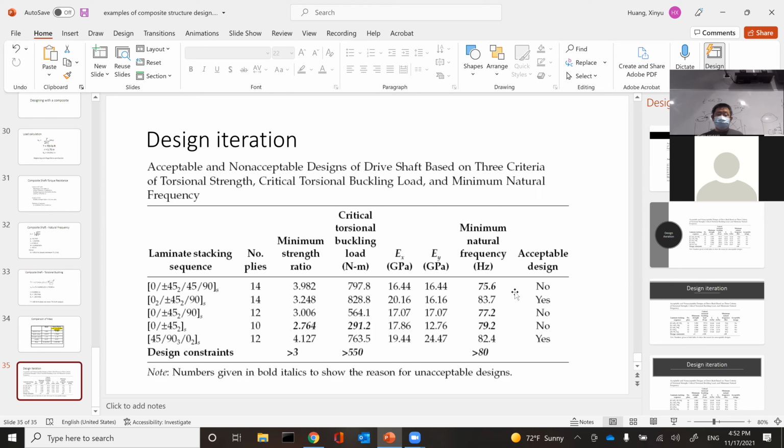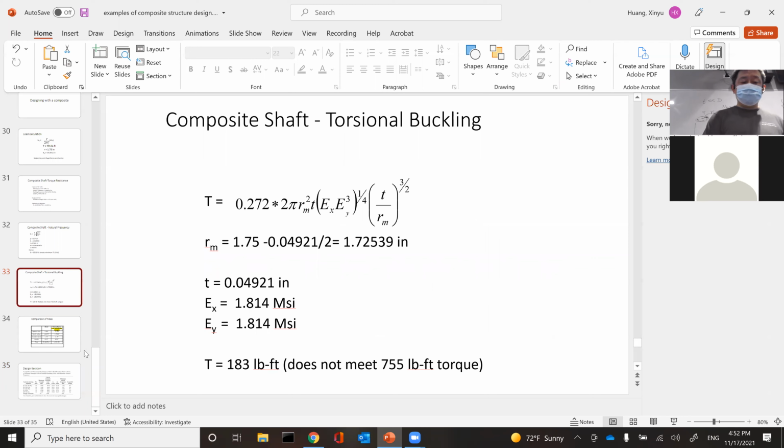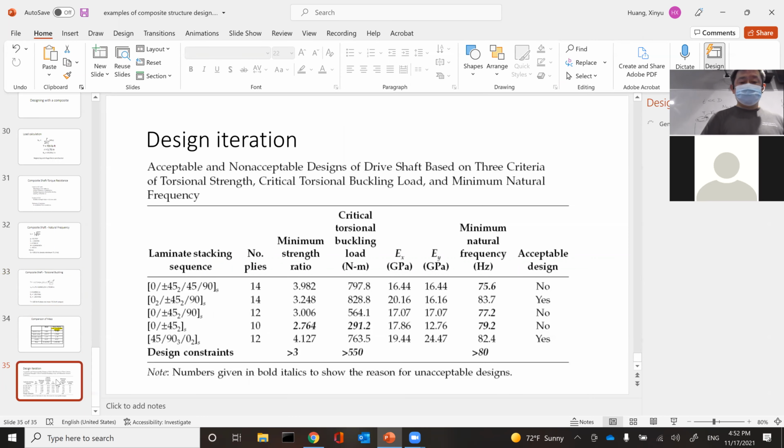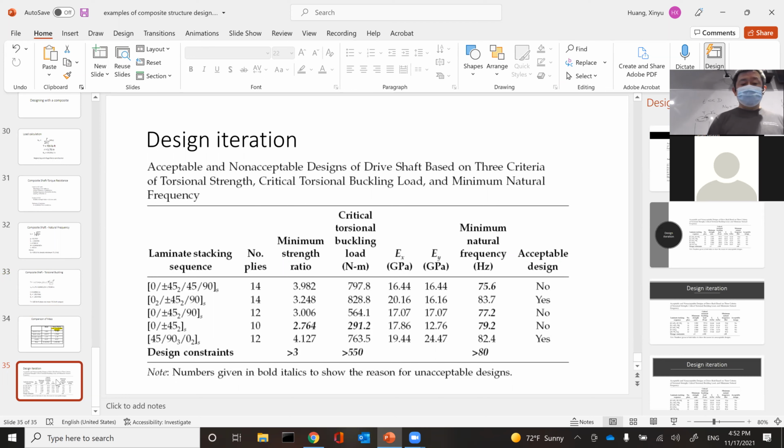This mechanical analysis basically gave you an idea how safe this shaft is. And you can actually do this with a simple tool like your CLT code that you already wrote. Of course, you use a few additional equations, like a buckling equation as well as a vibration equation. And then, of course, you can explore other layouts.